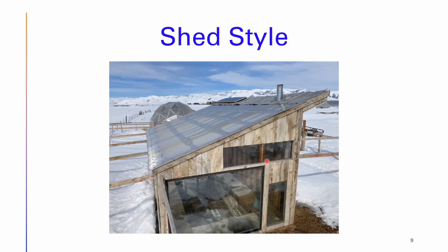The other thing I thought was interesting, and I don't really understand why people don't do it, is using glazing on a shed for an animal shed. I ended up turning this into my goat and chicken shed. You don't have to thaw your water out because you can capture the sun's energy, and your livestock can just drink their water without having to worry about breaking ice. So it's a clean and a smart solution. And the reality is the polycarbonate is as expensive as, or cheap, I guess, as your standard corrugated metal. So it's just a smart solution if you're building a shed for animals.